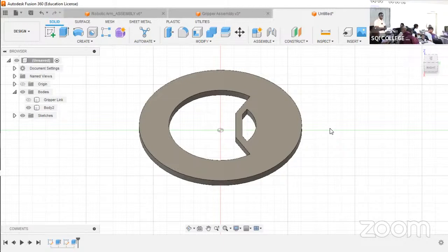Who else is having an issue before we continue? Don't extrude yet. I told you, click on this to go to a 3D view. Now go to extrude. Click on the areas to extrude, one after the other. So 3, 4, and then the outer one. This one, yeah. I can drag everything up. Make that 5 mm thick.